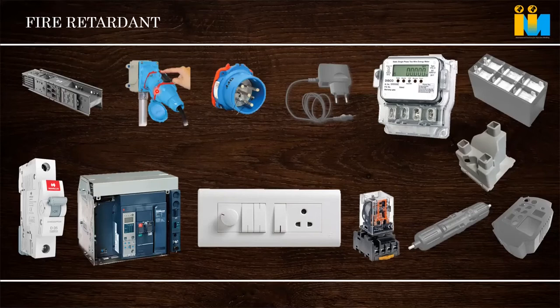Yesterday we discussed that with PC, if we need better chemical resistance or electrical property like PBT, then we make a blend and use these products. These plug sockets are PBT or PBT-PC blends. And mobile phone chargers are made of fire retardant grade polycarbonate. V0 polycarbonates are being used. For very low-end products, ABS fire retardant also comes into the picture for mobile phone applications. But majorly polycarbonate is used, due to regulation, because polycarbonate has better impact strength.